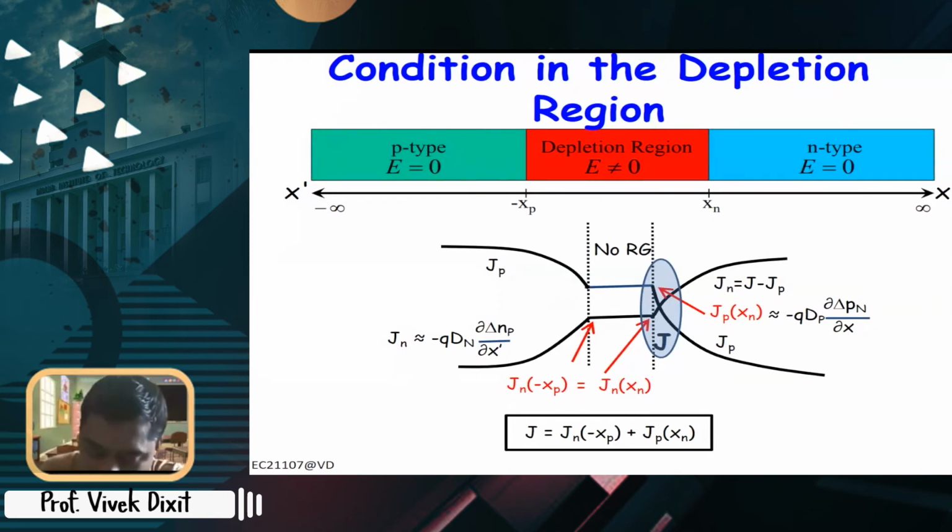Now you see here, this is the P side, this is the N side. So holes are diffused here, and they are basically reducing, right? Now here only the drift current is there, right? And then the diffusion current is due to the concentration gradient, which will be here, right? Now here, if you see the slope of these carriers, it is very large. So the current will also be very large here, right? And it will mostly be due to the diffusion.